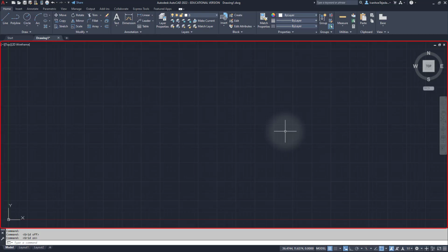The main area you see on your screen is the drawing area of your file. It shows the grid. This drawing area is based on the Cartesian coordinate system and it extends infinitely. The start point where x equals 0 and y equals 0 is identified by the UCS icon. UCS is short for the User Coordinate System. We typically begin our drawings at this start point, also known as the point of origin. Then we draw to the right and to the top in the positive quadrant of the Cartesian coordinate system.